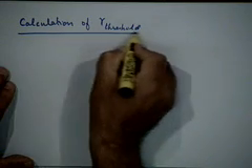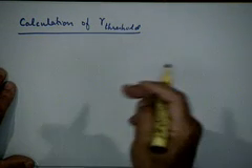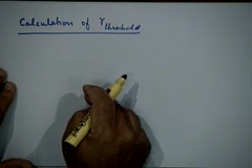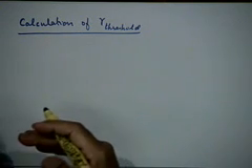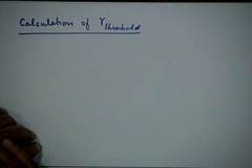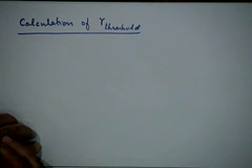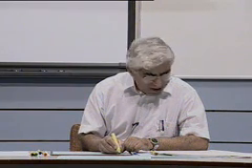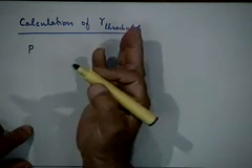You understand the meaning of gamma threshold? Gamma threshold is that value of S_i by N_B such that below this you will start seeing significant deviation of the output SNR curve compared to the linear curve. That is the definition. Now we can do this calculation by talking in terms of probabilities.